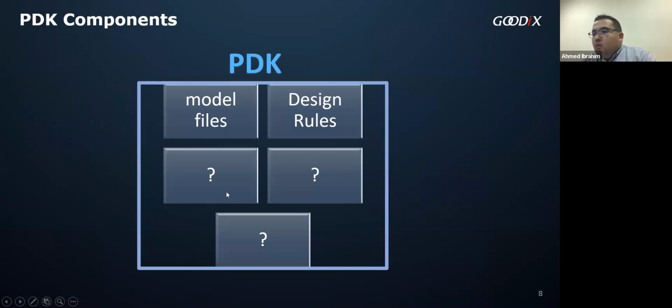Okay. So for the early BDKs, the combination of these two elements, the pre-characterized device models and the DRC design rules, became the first minimal requirements for fabless design. So as a person not related with a foundry, I just have the device models and the DRC. I can actually theoretically, nowadays this is of course impossible with just these two, but theoretically I can tape out a design. These were the first things that we refer to as BDKs, of course.